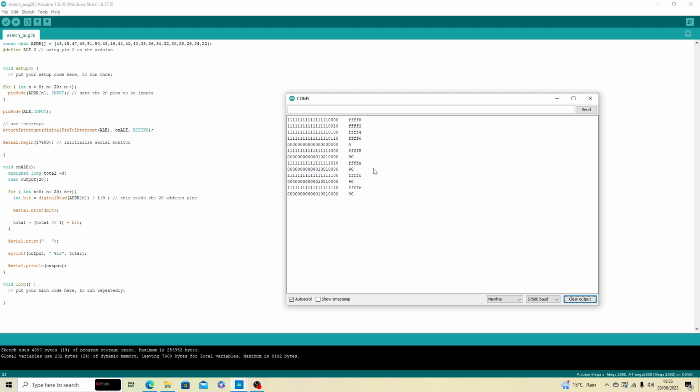Why is it not going 0, 1, 2, 3, 4, but going 2, 4, 6? Well, that's because the processor is reading 16 bits, so it has to move the pointer on in groups of 2. We have set on the data lines a no-op instruction, so the processor just moves on to read the next address, and as we've used resistors to hard code the no-op instruction, it's just moving on in sequence.